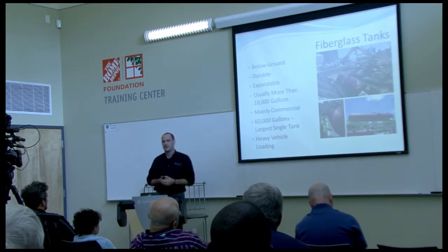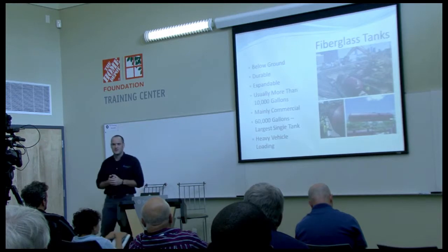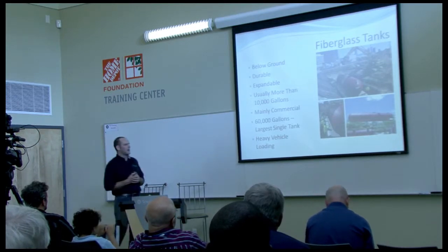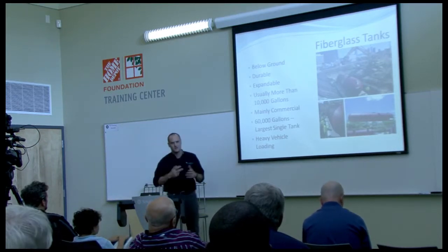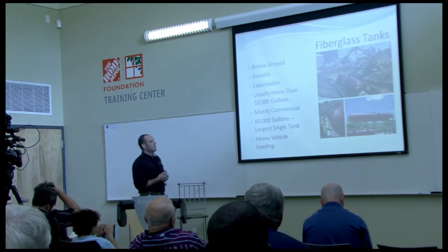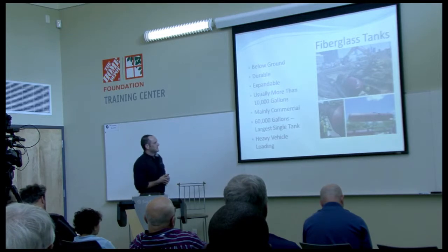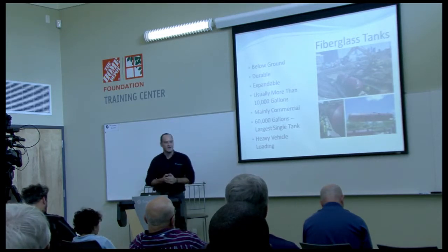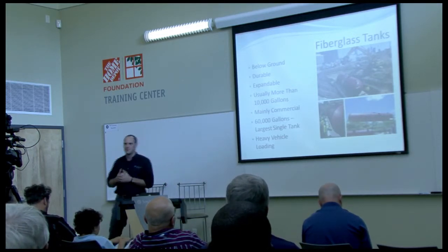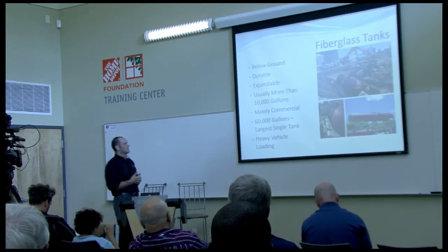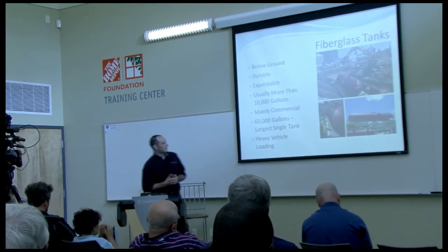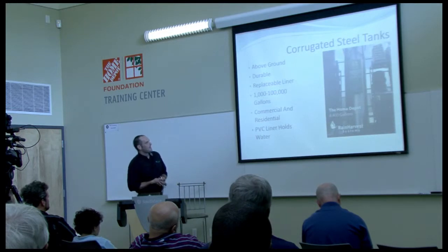These are the same tanks that are under every gas station in the United States. The water tanks are single wall tanks. The petroleum tanks are actually double wall tanks, so they're a little different. But these are very common tanks, very common in commercial applications. Again, you can get an H25 vehicle load rating out of it, so you can put the heaviest fire truck on top of these tanks. Again, very durable, tried and true technology.